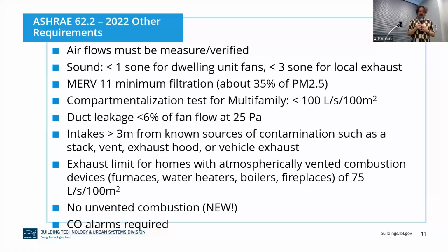And just a couple more slides on the residential side of things. There's a whole bunch of what we call other requirements that aren't necessarily, here is the airflow, right? There's things like, how sure are we that you've installed it right? So we have a requirement that the airflows are measured and verified. We have issues about if you install very, very noisy fans, people will not like it and they will turn them off. So we require the fans to be relatively quiet. Very recently, we've introduced a minimum filtration requirement. We use the US MERV reference here, but for those of you who think about filtration of PM 2.5, it's about 35%. So not fantastic, but, you know, small steps.